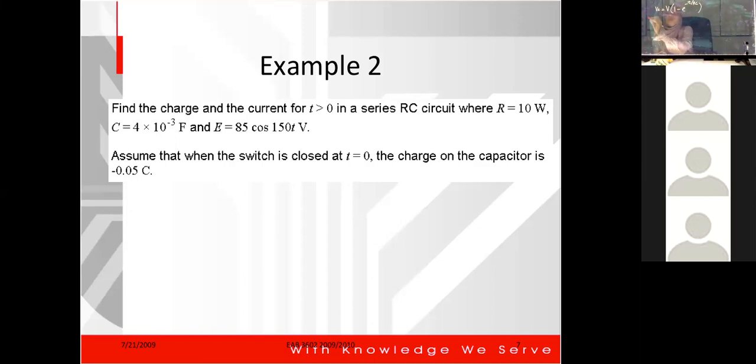Okay, so 1 over RC is equal to 1 over 5 multiplied by 0.02. R is 5, C is 0.02, so you will get 10. Betul? So the equation for VC is becoming VC is equal to 100 multiplied by 1 minus e to the power of negative 10t. Okay?